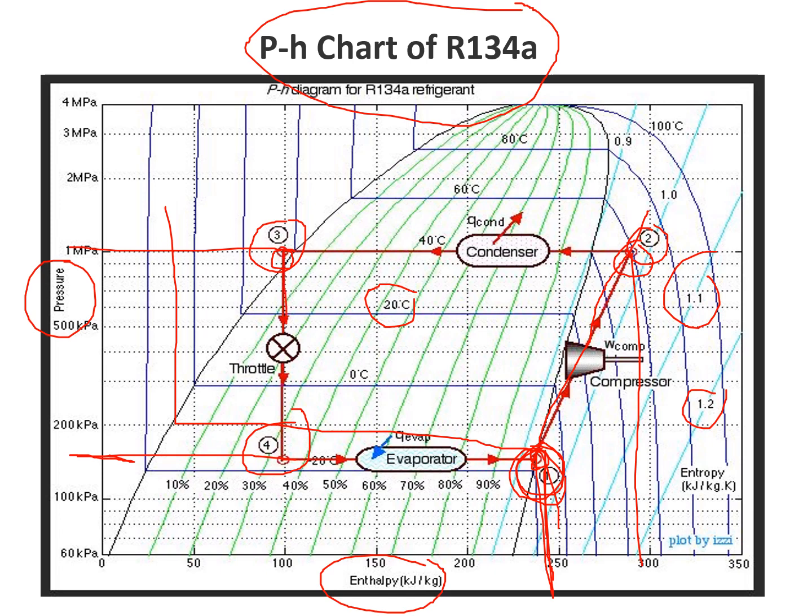Then from this 3 you can find out the enthalpy H3, and then you have the expansion process or the throttling process. Now you drop the pressure till the evaporator pressure along the same enthalpy line, because this is the isenthalpic expansion. So H3 is equal to H4, and your pressure is reduced here. Okay, so then 4 to 1, that is the evaporation, already you know.